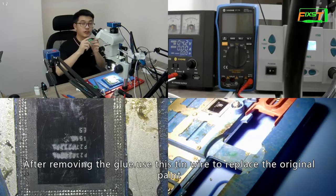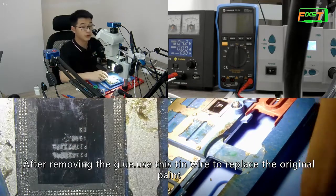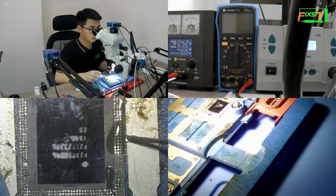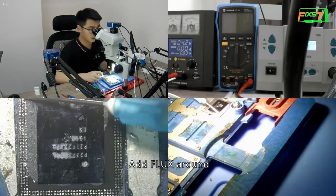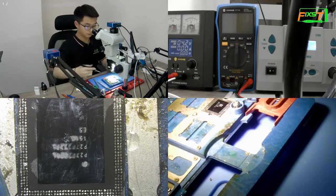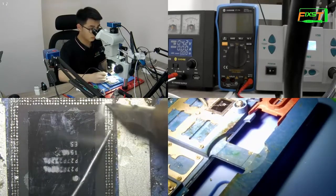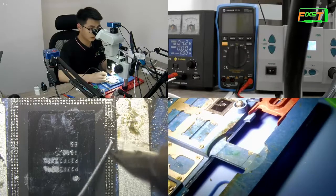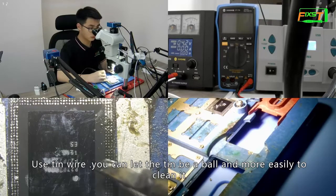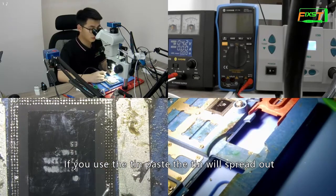After removing the glue, use this thin wire to replace the original paint. Add flux around. Use thin wire. You can let the tin become a ball and it is easier to clean. If you use tin paste, the tin will spread out.